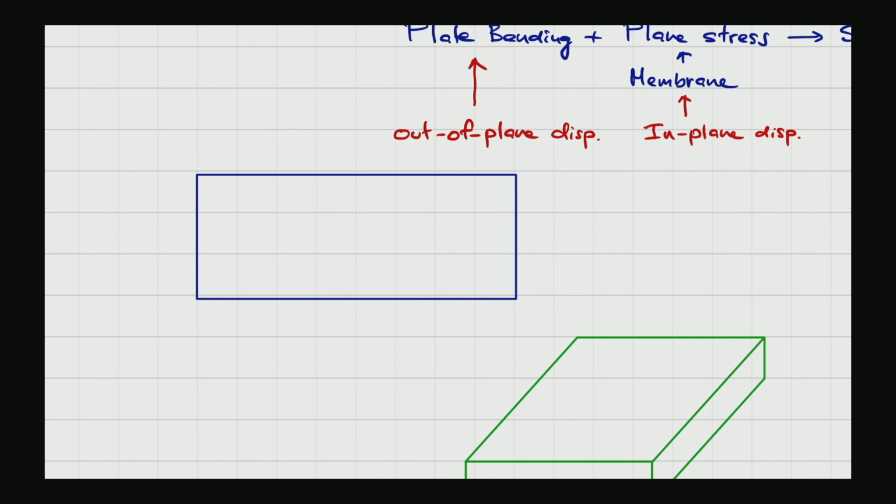But if possible, you should use the continuum element, such as the plane element, shell element, or the 3D brick element for the analysis of a thick structure like this. For example, like the foundation, a pile cap.